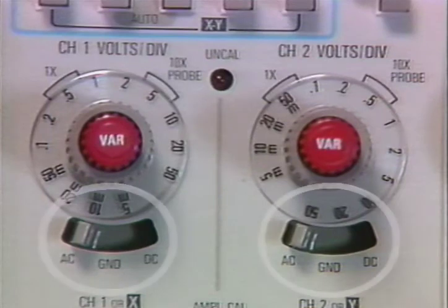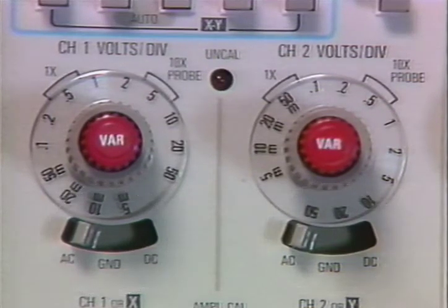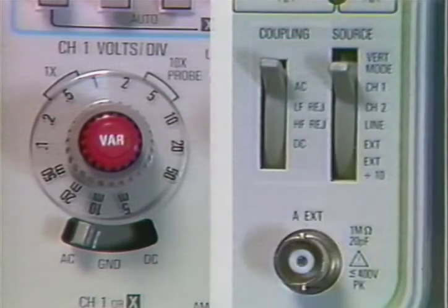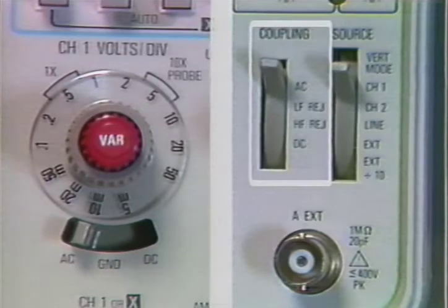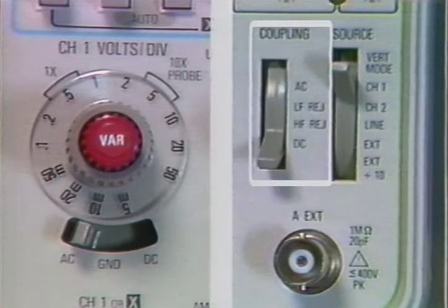Just as you may pick either AC or DC coupling when you connect an input signal to your scope's vertical system, you can select the kind of coupling you need when you connect a trigger signal to the trigger system's circuits. For internal and external trigger signals, you have a choice of AC coupling, DC coupling, LF reject, which rejects the low-frequency components of the input signal, or HF reject, which rejects the high-frequency components.